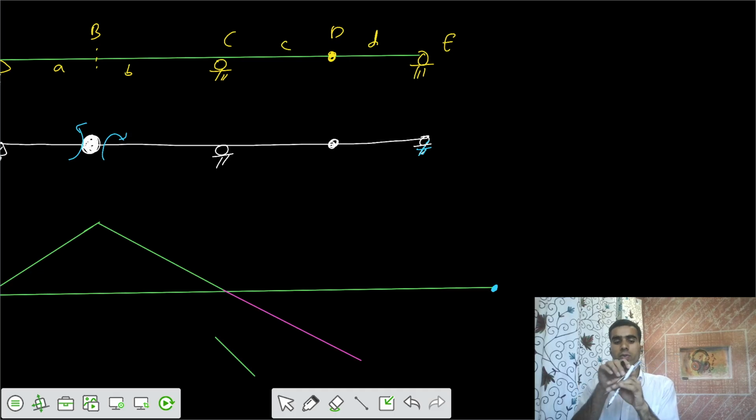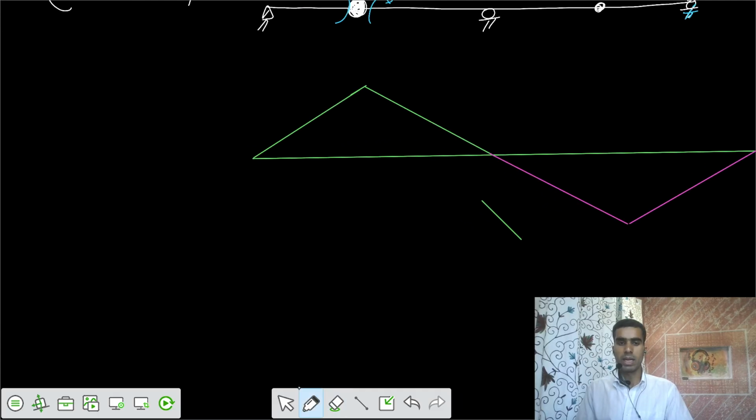Once we have the internal hinge here, at point D, CD has gone down in this fashion, but C is at the location of itself. C is intact, D is here, and for support E, we have to make sure it is also at its original position. So the profile CDE would be in this fashion, such that support C and support E are at the same level where they were initially. So this would be the variation of the ILD for moment at B.